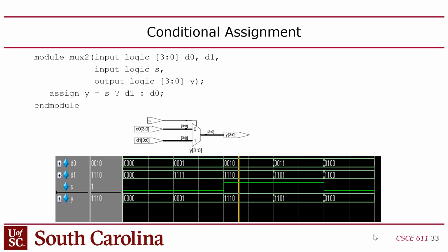the register file has an input called data in. That's the data that you write to the register. But that data could come from the ALU, or it could come from the memory, right? Or it could come from maybe a coprocessor, if you want to transfer a coprocessor register into a register. There's various places you can get data to put in the register file, but there's only one write port on the register file. So the way you deal with that is with a multiplexer, which allows you to select which source is routed into the data input on the register file. And hopefully you guys saw some examples of that in 212, right?